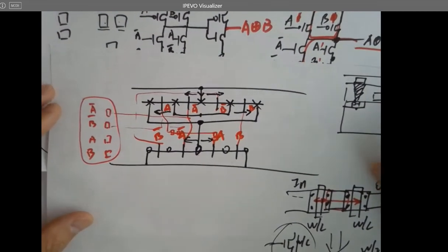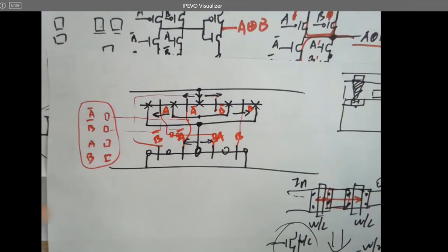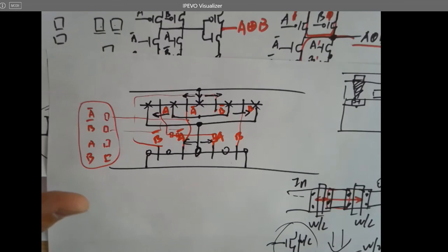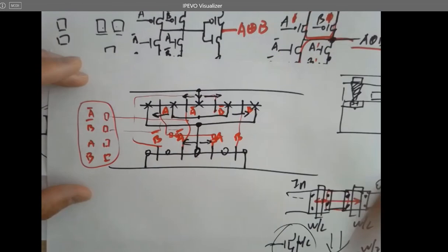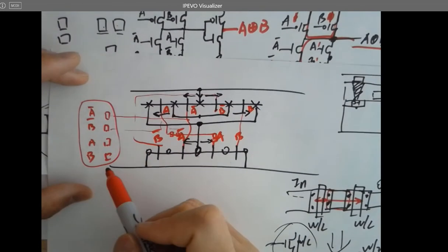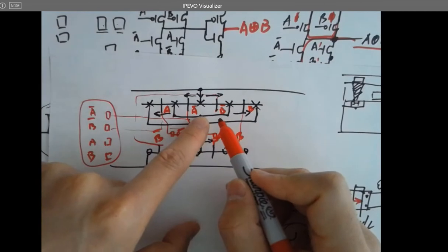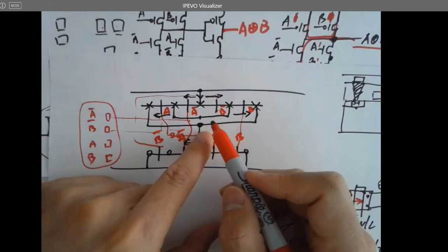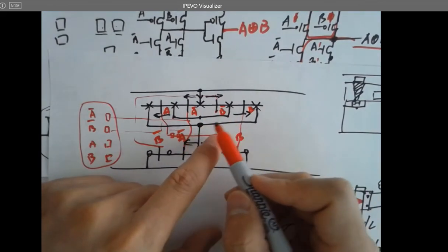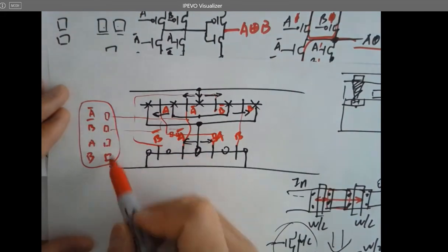Okay. So when you are using the entire block as a module in the library, you just want to directly drop it in the layout view and reuse it in the future for the upper layer circuit. So you want to have all these signals available. You just don't want to have all these signals inside the circuit. So whenever you are connecting all the signals to whatever inside, you still have to consider the metal 1, metal 2, poly layers, not shorting all these wires, right? You just have all these pins available on the left.